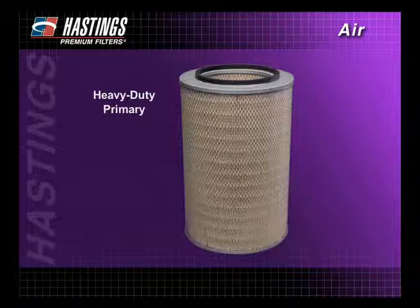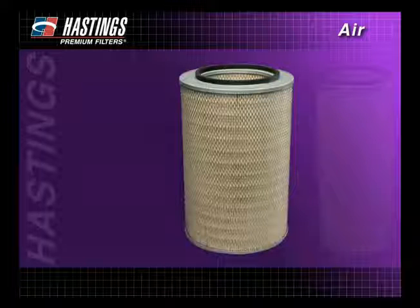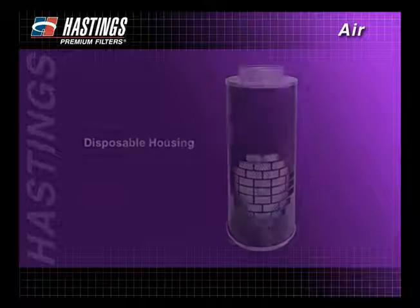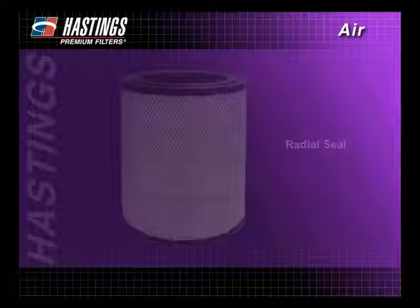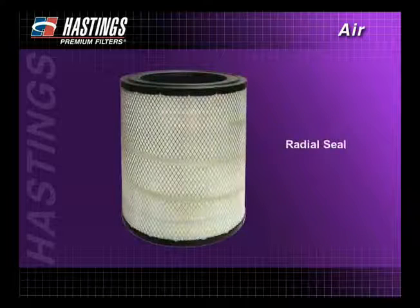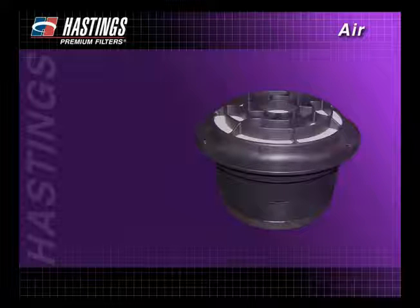There are several types of heavy-duty air filters. Heavy-duty filters include primary filters, which usually have metal ends and are available in both standard and long-life models. Heavy-duty secondary filters, which are used to seal out dirt while the primary filter is being serviced. Disposable housing filters, which are designed with both the filter and housing in one unit and are easy to replace. Radial seal filters, which are designed with molded ends to make servicing easier and more cost-effective. And corrugated straight-through flow filters, which are designed to have high flow and high capacity in a more compact filter.